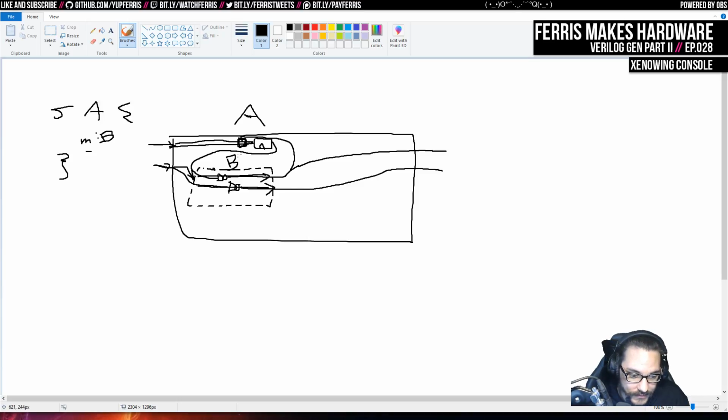We can actually avoid doing all of that if we just flatten the whole hierarchy, because since we don't have any combinational loops ever, we actually know that if this was a flat graph, we would only have to propagate the signals in A. So for example, this would go to here and then through here and into the output, and we're done. This would go to here and to this register, and that also includes propagating this signal, because it's all the signals of A, and then we're done, and then this also propagates. Yeah, exactly, because this propagates through here and out this way.